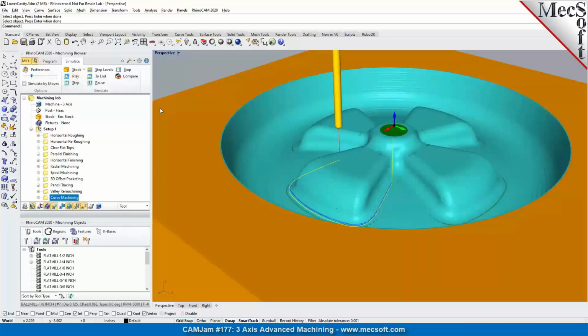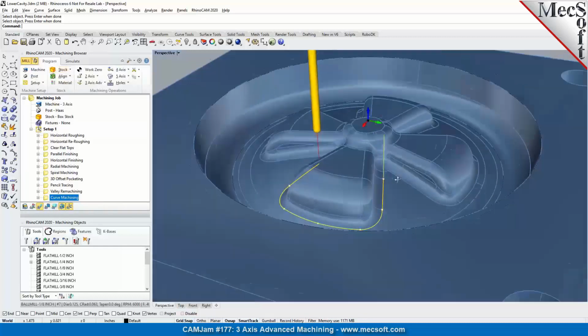And also I would avoid using any flat end mills or square end mills for pencil tracing operations. As Joe pointed out, you're going to end up running into this jaggedness on the toolpath. So try to use a radius tool, which could be either a corner radius tool, a flat mill with a slight corner radius, or typically a ball mill cutter for pencil tracing and remachining toolpaths.